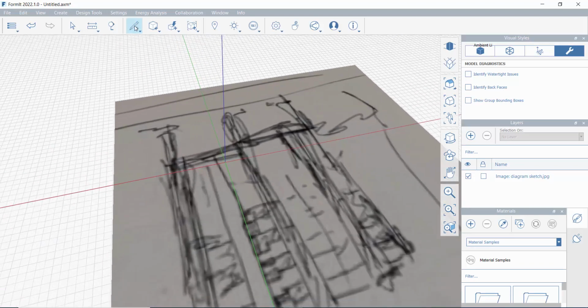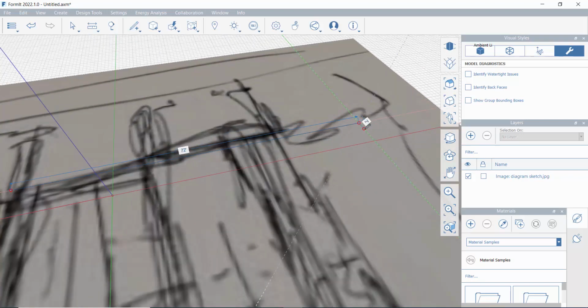So to do that, my pencil tool, there are a bunch of different ways to build walls and things. Okay? Eventually, you're going to start to learn your own. I'm going to go the longhand method by drawing individual lines, so you can kind of see how the program's coming together. So pencil, line tool, I'm going to start right here. I know that that was supposed to be 56 feet, so I'm going to go ahead and go 50. Actually, I don't know. I'm already changing the design. I want to go further because it seems fun. 72 feet. I'm going to make that wall 2 feet thick.